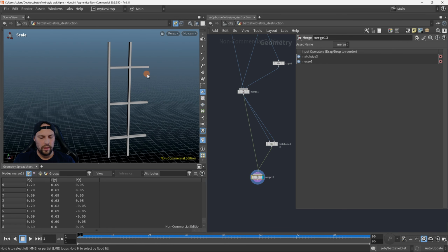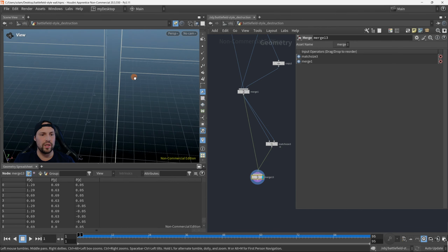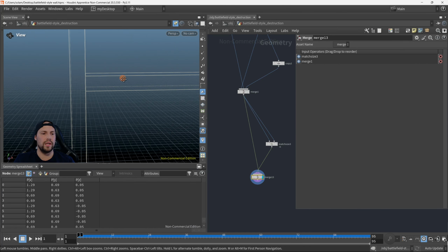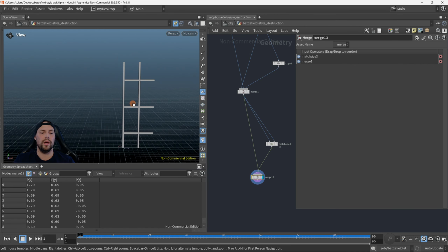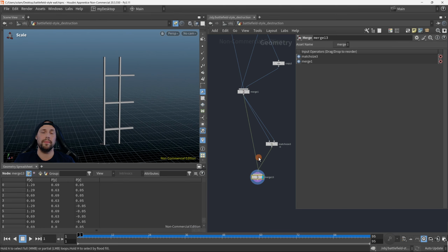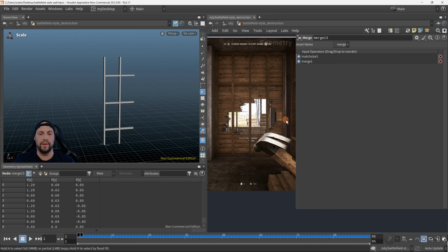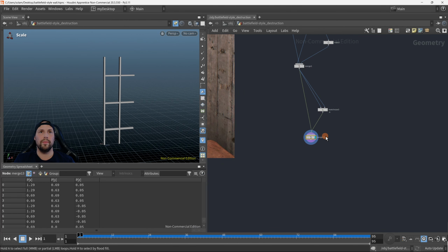Great. Let's press W on our keyboard with our mouse over the viewport and check for intersections and see how flush it is. There are no intersections. It is perfectly created geometry. Great. This is an absolutely fantastic beginning, but we're far from completing this. There are still more sections for us to create. So we have 1, 2, and I need a few more. So let's repeat those steps.